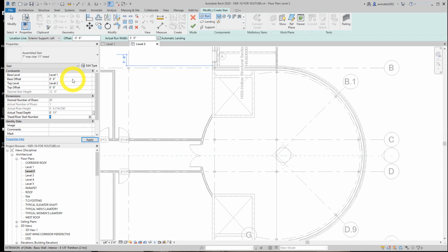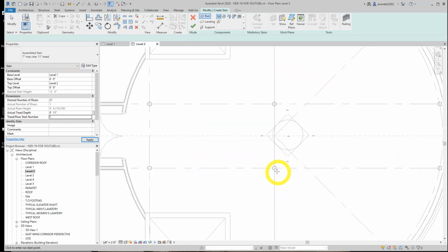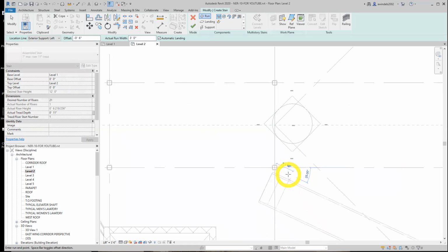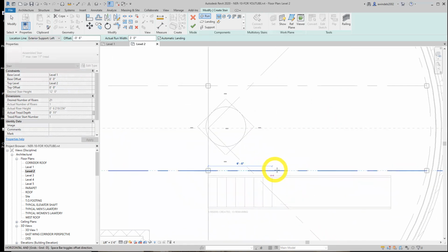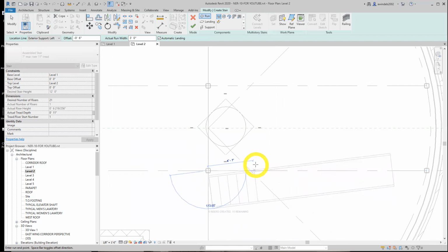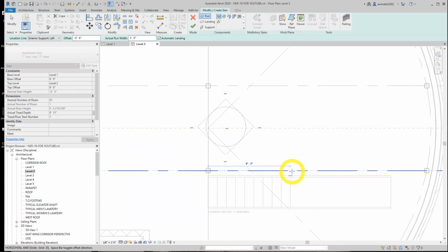So on page 488, we're going to pick a point in the center of this column after we didn't leave our command. And we're going to go this way. You see the risers being created and remaining, and that faded text to the lower left there. Mind that. And the second option, we're just going to watch how many stairs get created. We're going to hover, and when this stair gets created at 9 feet 2 inches, you can see in the blue dimension up in here, we're going to stop.